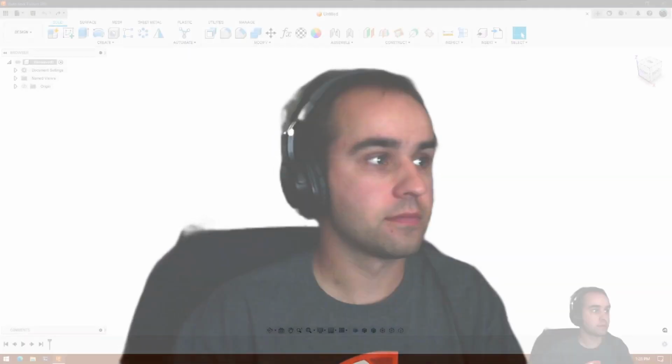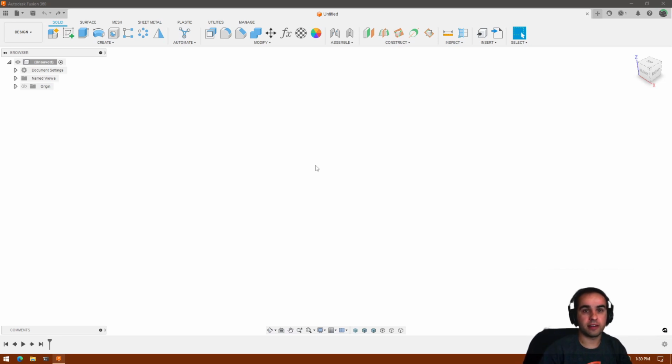To start things off, I'm going to go over the basic terminology and layout used by CAD software, and then go through the basic workflow used to create parts in CAD. So here we have a blank document open in Fusion 360. And when creating something in CAD, there are going to be two main steps used repeatedly to create parts. There will be creating a sketch, and then there will be performing one or more 3D operations based on that sketch. So I will start off showing that in Fusion 360.